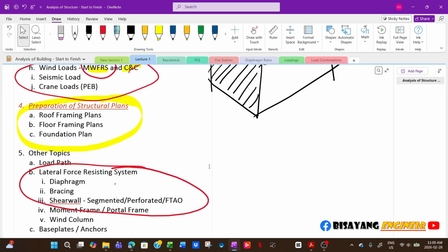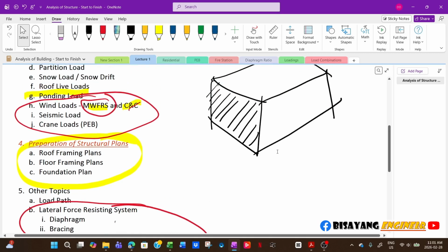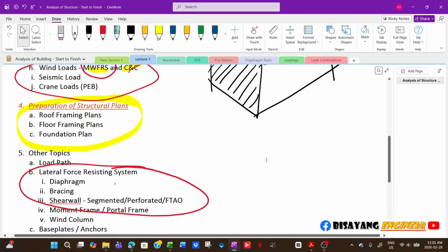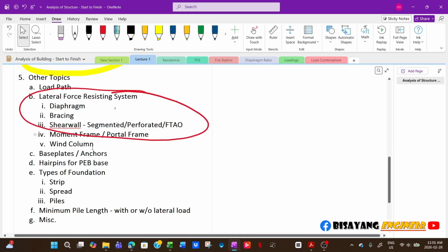We will get a sample geotechnical report, read the report, and see what the recommendation would be, and then try to lay out a possible foundation plan, like if it's continuous footing, spread footing, or grade beams on piles. And after that, we'll be discussing these other topics here.